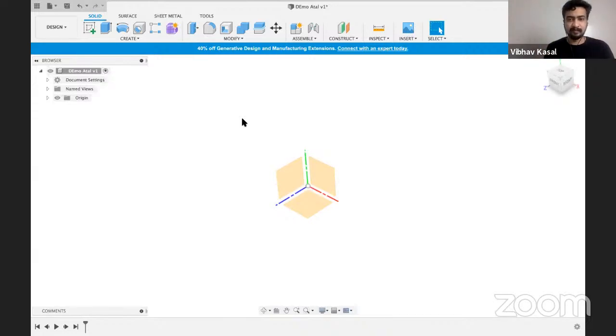Or you can just generate an OBJ or object file, or a stereolithography or STL file. You can generate an STL file or object file and import it into the software that comes with the 3D printer. There you can do the slicing and add the hanging and supporting structures, and you can set what the infill is, all of those things.